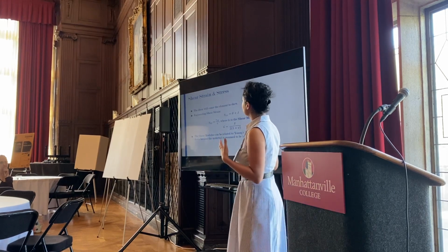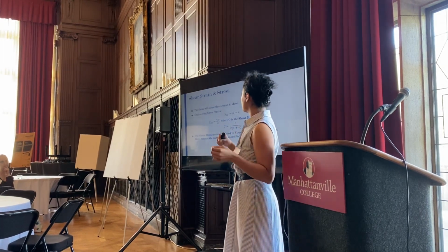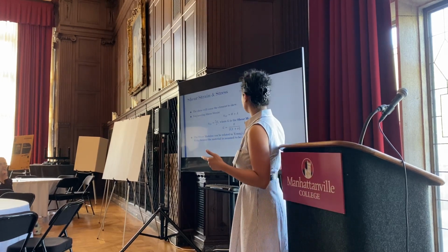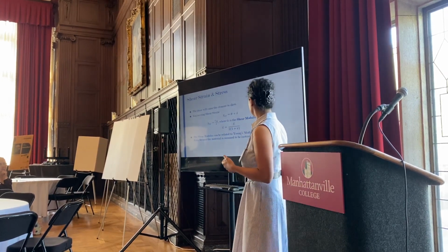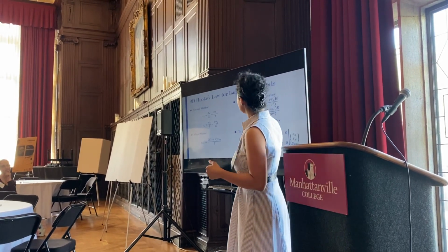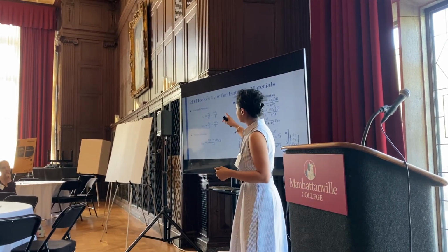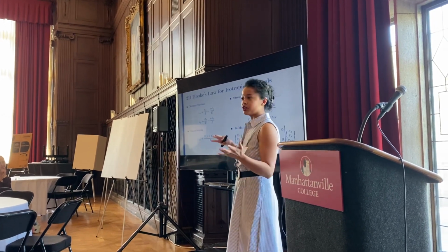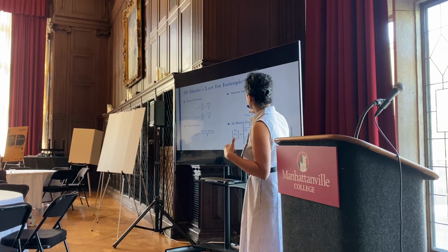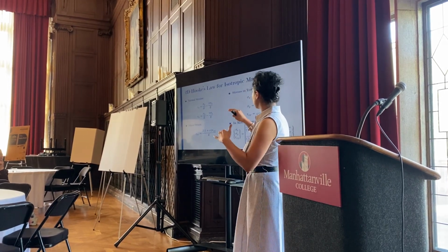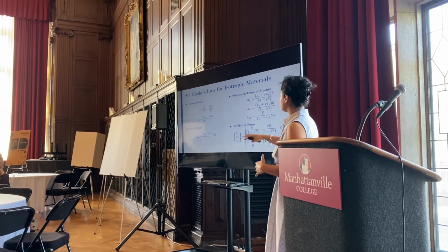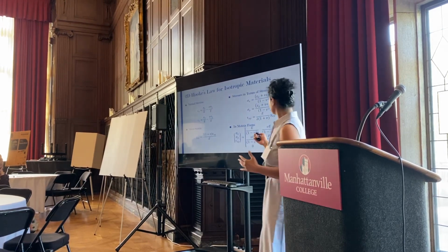Our engineering shear strain can be related to the shear stress using the shear modulus, which is G. The shear modulus can also be related to Young's modulus and Poisson's ratio because the material is isotropic. So in the second dimension, we have our normal strains and our shear strain, which we saw in the previous slides. These are then put in equations that are equating to our normal stresses and our shear stresses. Once we have these three equations, we put it into a 3x3 matrix.